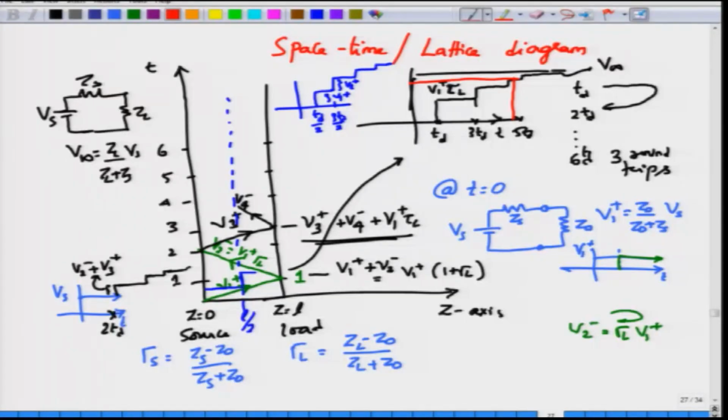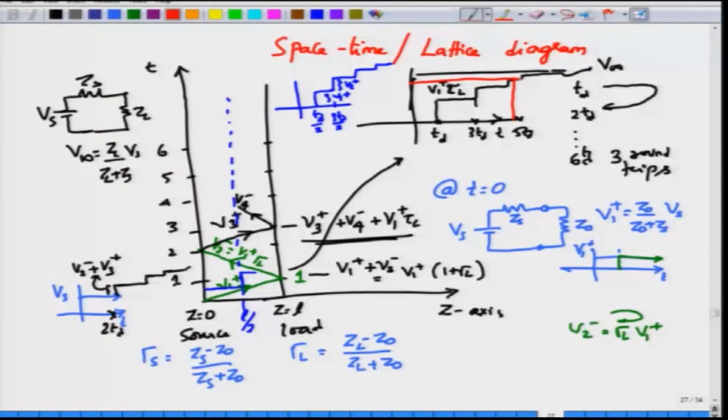In the case where there was no transmission line, any switch change or any sudden change at t equal to 0 because of the source IC changing would be immediately available to the load. There is no ambiguity whether the voltage that the load IC is seeing is actually less than threshold or greater than threshold, that would have been immediately available. However, now although the final voltage may be greater than the threshold voltage, it takes sufficient time. So, let us say it took about 5 Td because of the non-desired but present transmission line, you would see that the voltage reaches its threshold voltage at 5 Td, right.